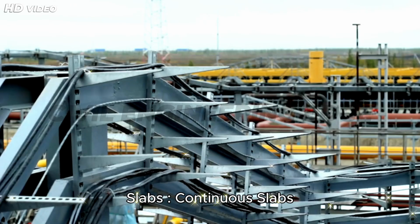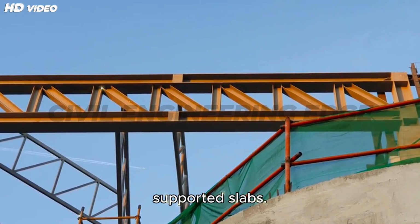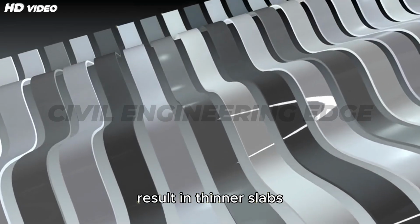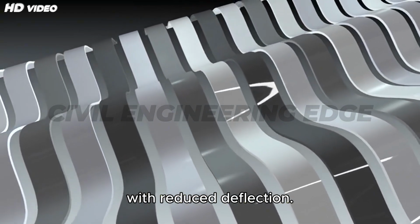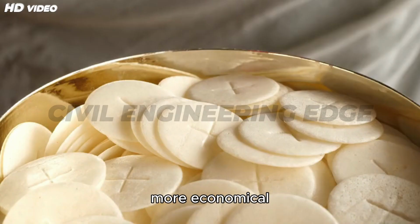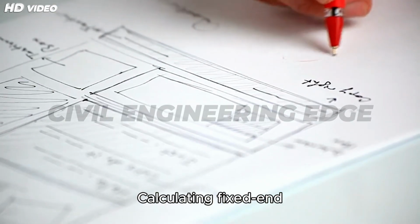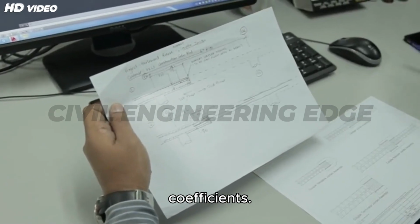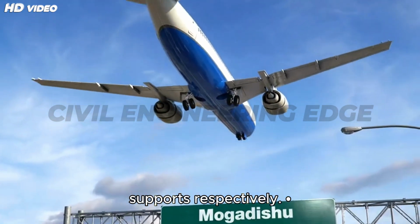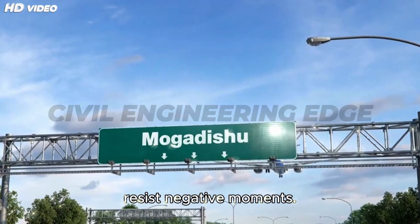Design of continuous slabs. Continuous slabs span across multiple supports and are more efficient than simply supported slabs. They reduce bending moments due to moment redistribution and result in thinner slabs with reduced deflection. IS 456:2000 allows moment redistribution up to 30%, enabling more economical designs. The design involves calculating fixed end moments or using moment coefficients, designing for positive and negative moments at midspan and supports respectively. Anchorage and development length are crucial at supports to resist negative moments.